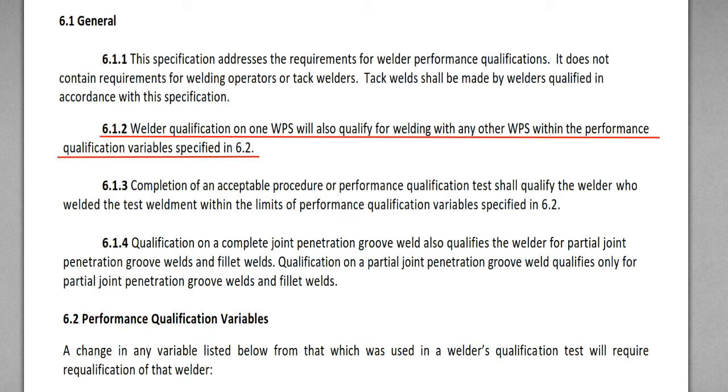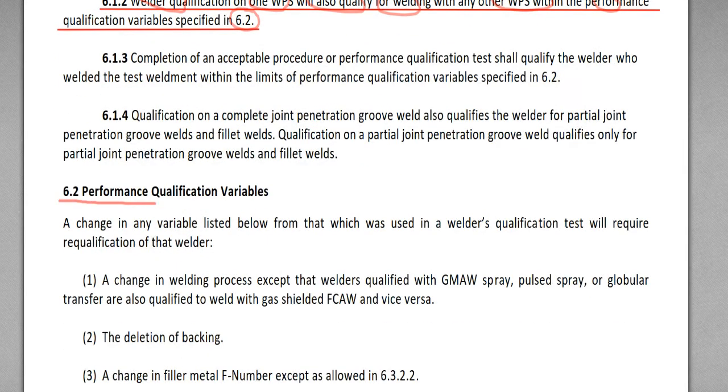6.1.2 Welder qualification on one WPS will also qualify for welding with any other WPS within the performance qualification variables specified in 6.2. 6.2 is performance qualification variables.